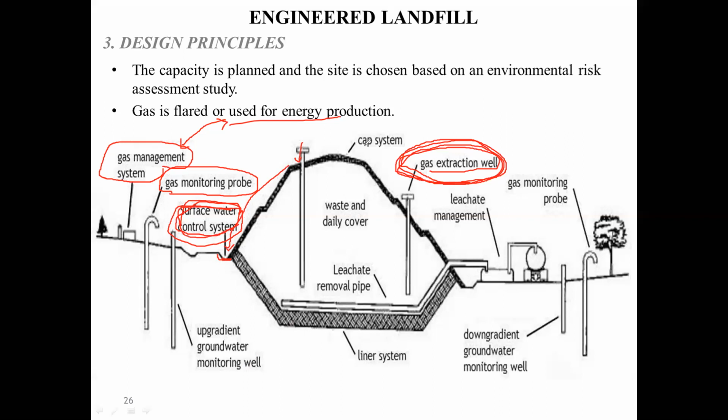Then you design the cap system. Cap system is nothing but covering the top surface of the landfill. That again depends on what quality of material we are going to use. See, if you have done everything properly, but you have not covered it with the proper method or proper system, again the vertical spreading of the waste is going to take place. Odor and pathogens or microorganisms which develop are not going to be controlled if the cap system is not designed properly. So we take care of the cap system, the cap covering system.